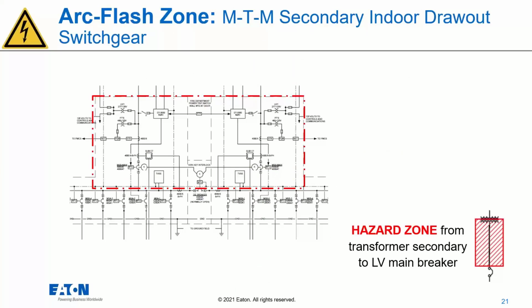All right, so in this case, we're looking at two scenarios, right? So looking at the open transfer switch or this piece of draw-out switchgear, we're going to be looking with and without that secondary relaying and the secondary CTs, and then with those features back in there, and seeing the comparative energy levels. All right, so we're looking at no relay, no secondary CTs, and we're just relying primarily on that pole-mounted vacuum recloser that's located upstream.